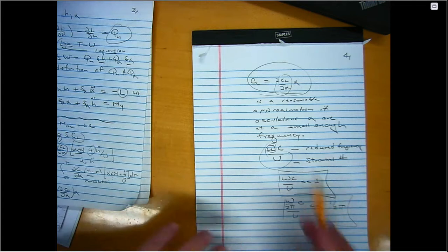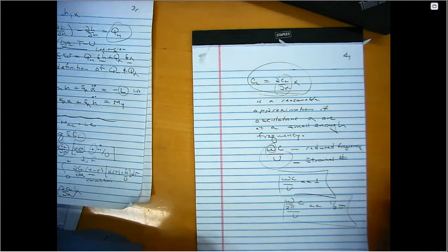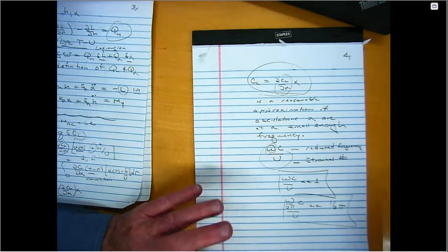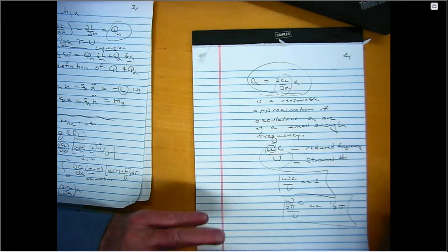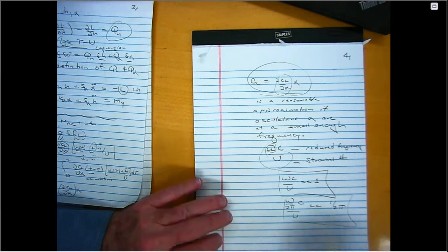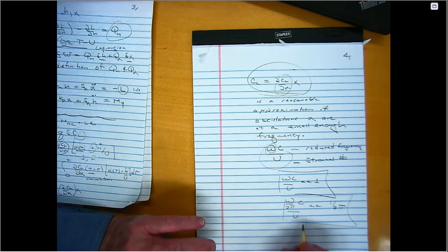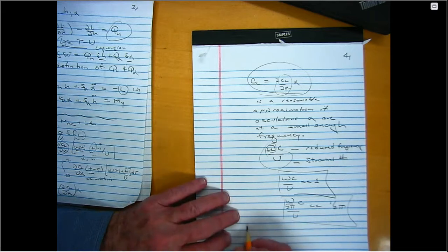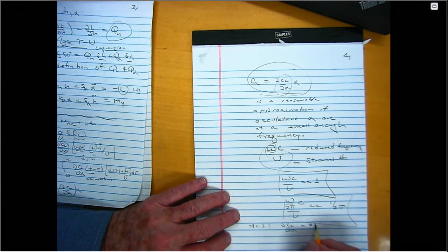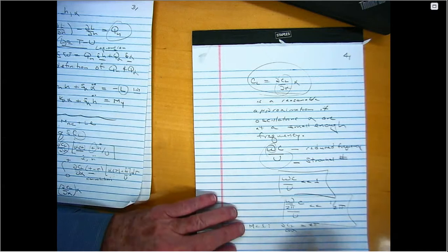So in that case, CL basically just depends on Mach number. So I'll tell you the two classical formulas for dCL/d alpha as a function of Mach number. And it turns out it depends on whether Mach number is greater than 1 or less than 1. Okay. So if the Mach number is less than 1, dCL/d alpha is basically 2 pi. See, what's the 2 pi going on? 2 pi divided by the square root of 1 minus M squared.